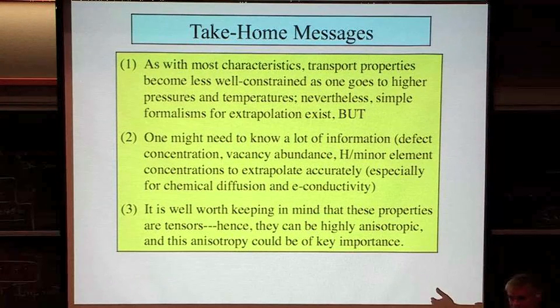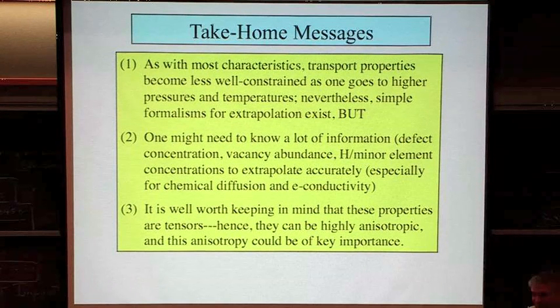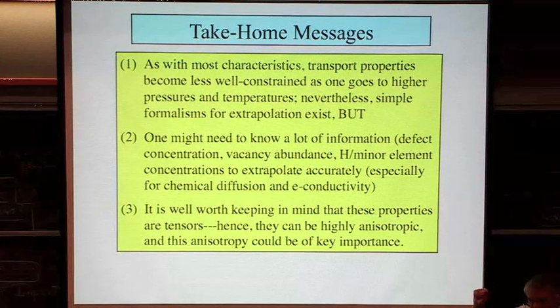But my guess is that the answer you'll get will be 5 watts per meter K or something like that, give or take a little bit, or 3 watts per meter K, because it is a fairly coarse thing. And remember, the numbers we're talking about are not so hugely variable that, when you put them into the square root of kappa t, the square root of them is going to change things dramatically. So it's a possibility.